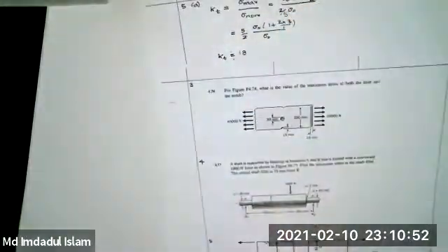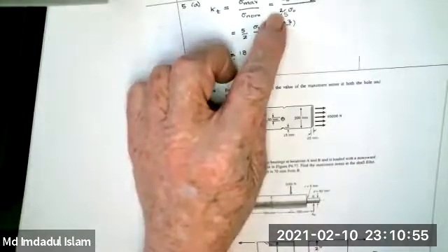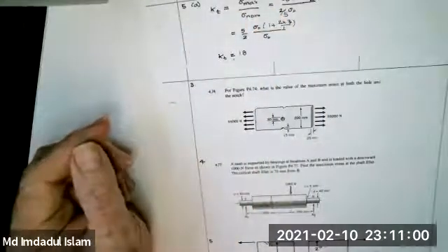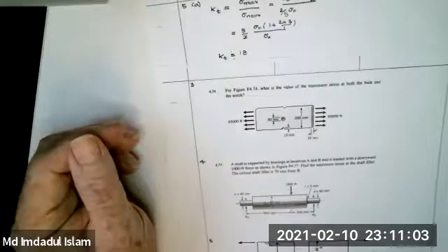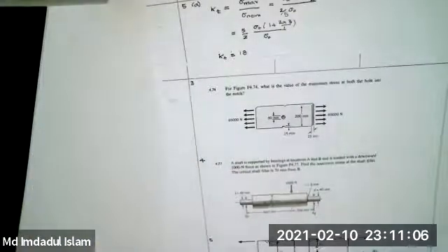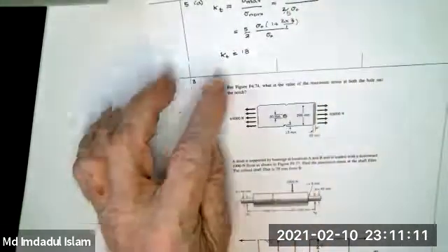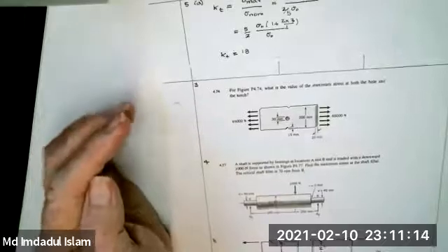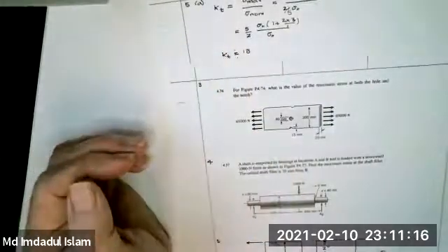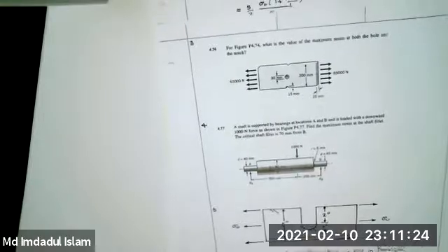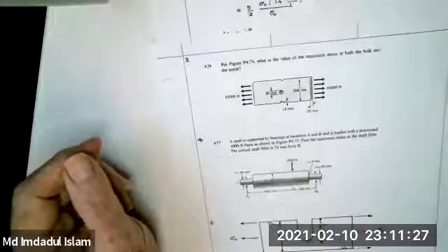But I multiplied it by the average stress in here, which I divided by the average stress in there. And so I had an integral factor of 2 upon 5, which increased the stress concentration factor by 5 upon 2. In other words, because the stress is going to be bigger, I'm going to apply that to the stress concentration factor. And so, doing the same sort of thing you just asked me about, you get a rough estimate of 18. Whereas if I hadn't done that, if I just put this as sigma naught, which would be the answer for an infinite plate, then I would just get 7. Okay. So there's a little bit of judgment doing stuff like that.